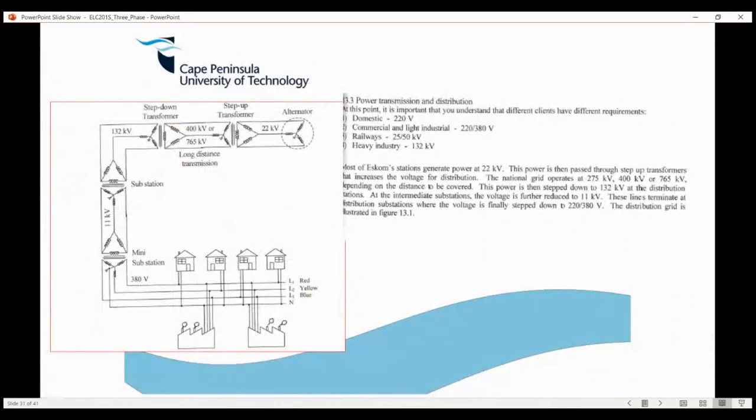Yeah, so there's a typical setup on obviously on land, and also on board with something similar, but on a smaller scale. Alternators connected in star. Goes to a step-up transformer, which is a star delta, steps up the voltage, low current, high voltage, that gets transmitted, and then what happens is it steps down again, and delta star, or the primary side, secondary side, then go delta star,